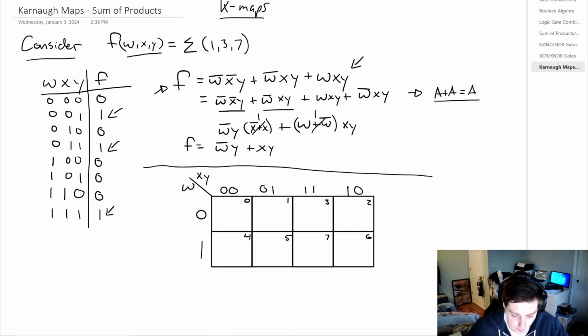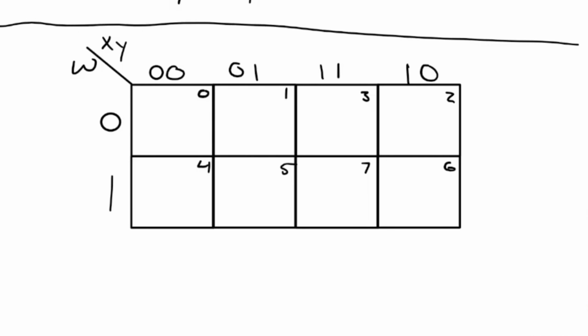All of these steps are nice to know when you're learning the fundamentals of logic and electrical engineering, but what we want to do is take it a step further and start to make things easy. So to do that, we introduce a concept called K-maps. With K-maps, we set up a table of however many cells we have for combinations of our inputs. In this case, we have 8 possible input combinations, so we have 8 cells.